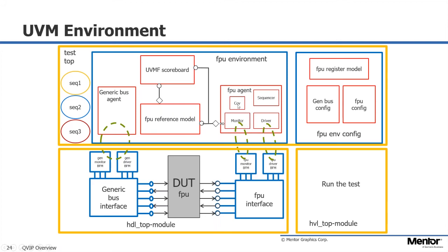The agent can use that to collect some coverage itself. It can feed that back over to a reference model, say. That reference model is saying, given this stimulus, I expect to see this out the other side. A scoreboard will say whether or not the received packet is what I expected. You might have a coverage collector in your environment.